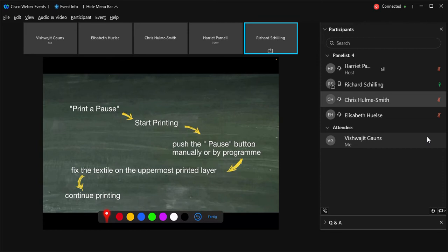In order to integrate textiles into an FDM print, you have to choose them carefully. And the textiles have to fulfill certain requirements. One of them is obvious. It's the temperature. The melting temperature of the textile fibers should be well above the temperatures at which you process your filament, so as to not melt or shrink in a significant way the textile which you want to integrate, and not having a lump later on instead of a textile. So that's the one thing.